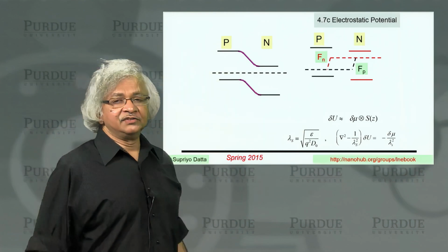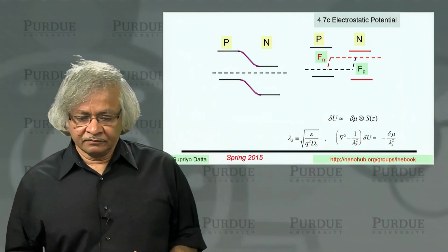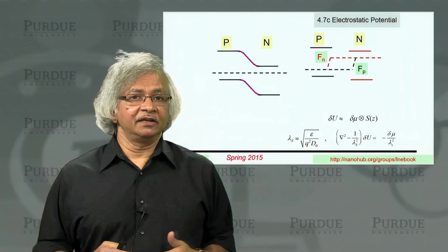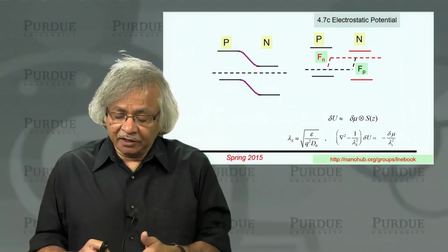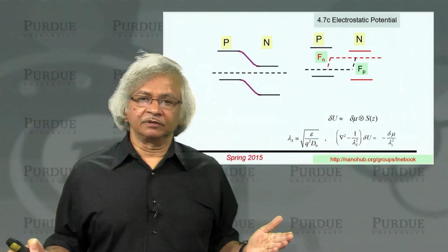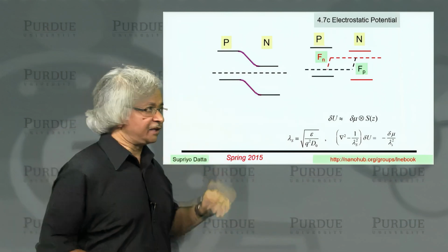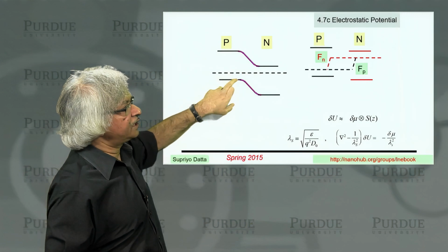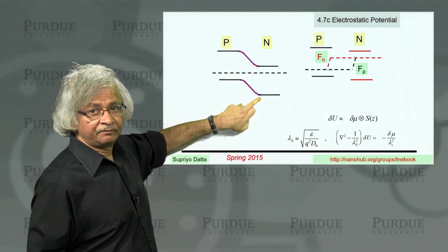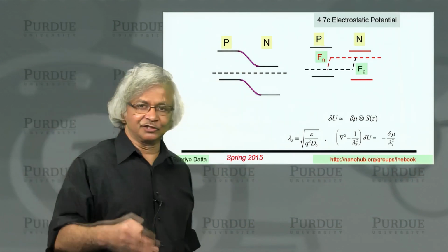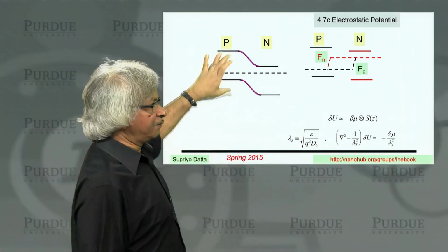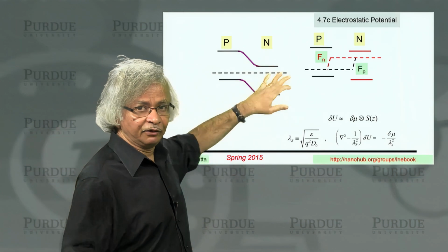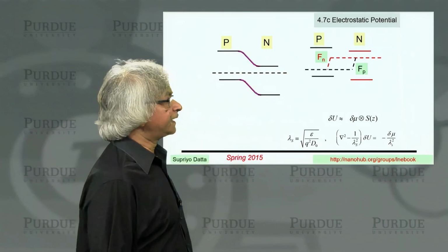What it says is, just as at equilibrium the temperature is the same everywhere, similarly, here at equilibrium, the electrochemical potential is the same everywhere. That's an exact statement. On the other hand, the electrostatic potential has already got a major variation right there. And so if you believe that current flows due to electric fields, we have a problem here, because there is a built-in electric field even at equilibrium with nothing flowing. I mean, no net flow.